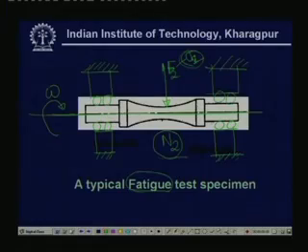That means you give a cyclic tension compression, tension compression, in reverse directions for a few cycles, then the wire will break. So, this is what we understand by the fatigue failure of the material under cyclic loading. Now, this experiment was originated by R. R. Moore, and that is the reason this experiment is very popularly known as Moore's experiment.